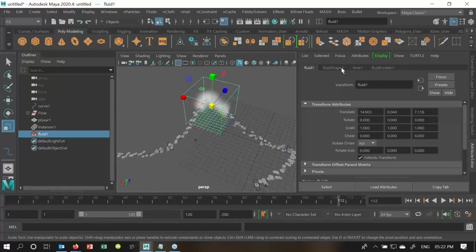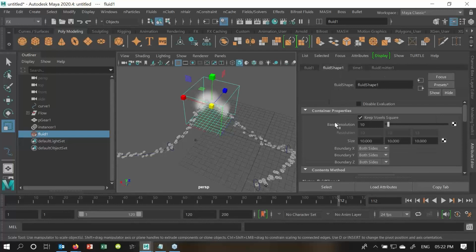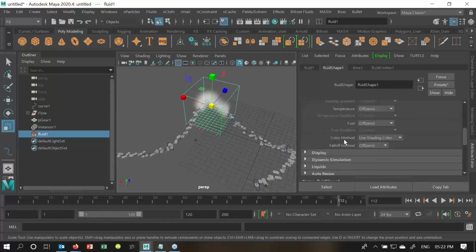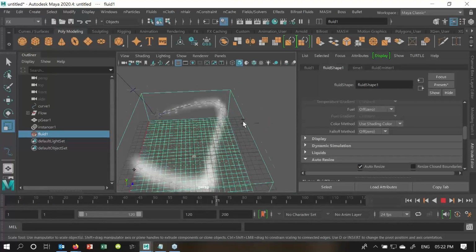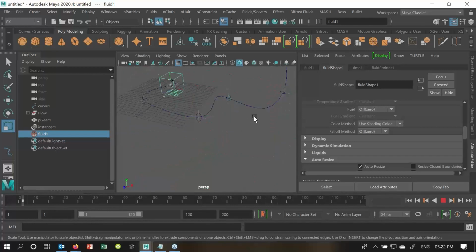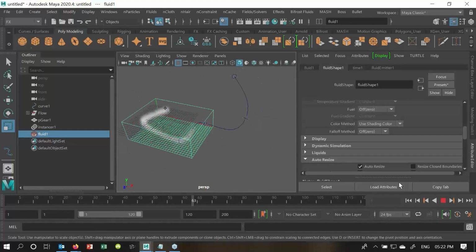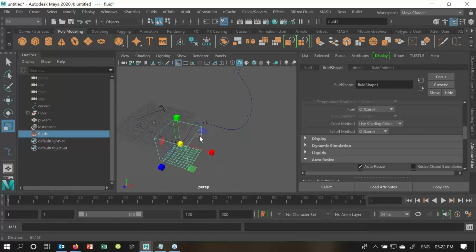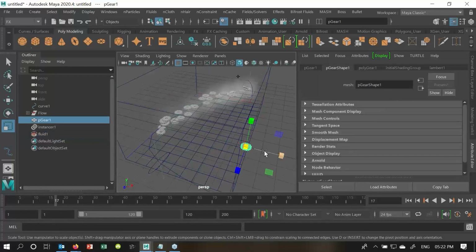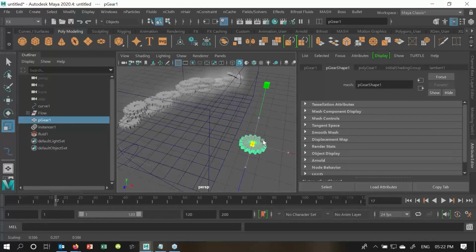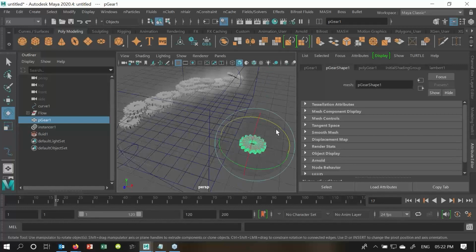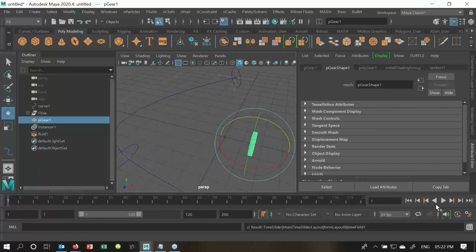Simple, select the emitter, fluid emitter, fluid shape 1, go over here. We have auto size, select auto size on. Now it starts to emit where my particle is coming. See this? Now if I want to change my particle shapes or the rotation, I'll select my main particles or objects, and try to reduce and increase the scale. Select this, right?